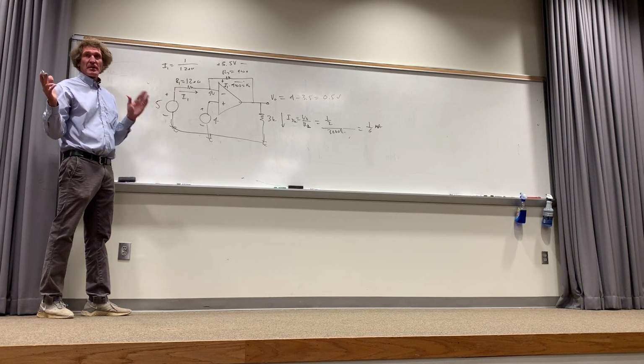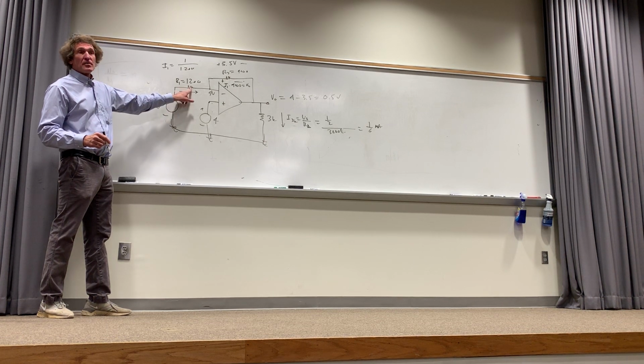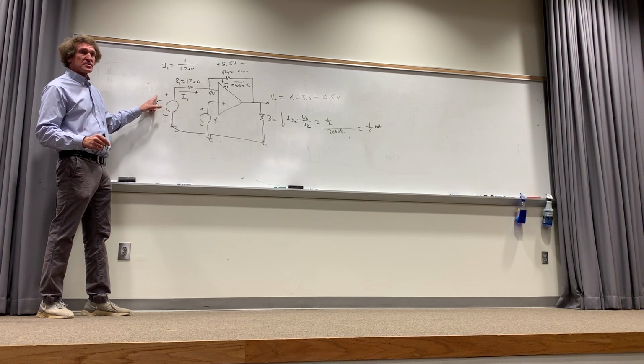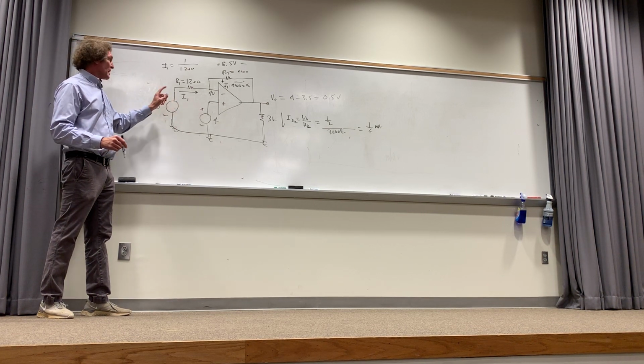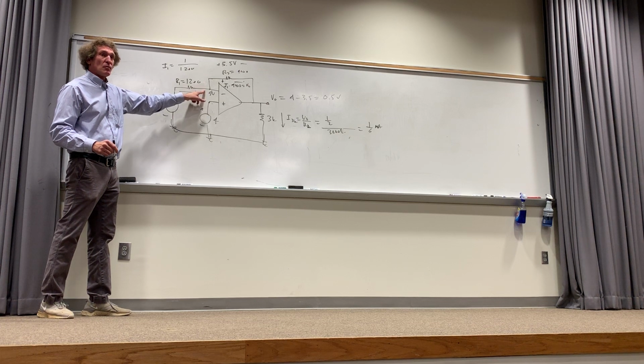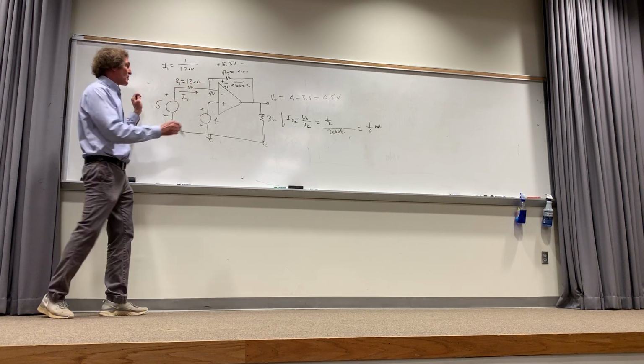Now, just bear with me here. It's 1200, right? 1200 ohms, and this is 5 volts. Is the polarity positive there on top? Yes. Well, that's 5 minus 4 is 1. 1 divided by 1200 is that current, correct? Now that current flows here.